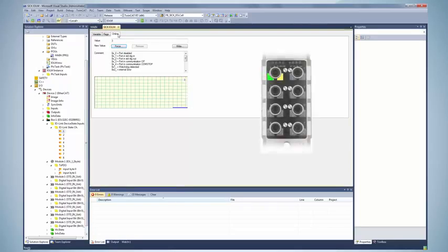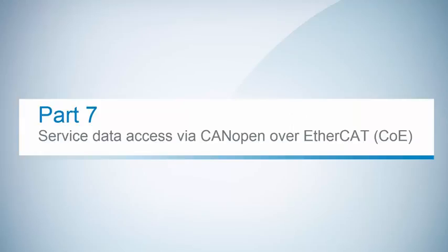Here we can check whether the sensor is in communication mode. Value 3 shows that the sensor is currently in communication mode. If no sensor is connected, the displayed value changes to 160, which is in hexadecimal A0. If a wrong sensor is connected, the value 48 is displayed, which is 30 in hexadecimal and is defined as an invalid device ID.